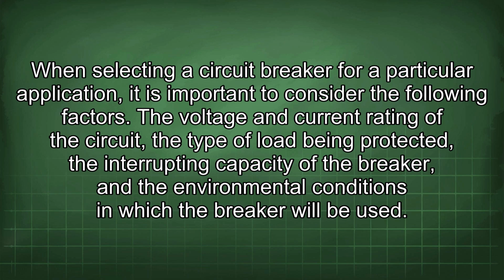When selecting a circuit breaker for a particular application, it is important to consider the following factors: the voltage and current rating of the circuit, the type of load being protected, the interrupting capacity of the breaker, and the environmental conditions in which the breaker will be used.